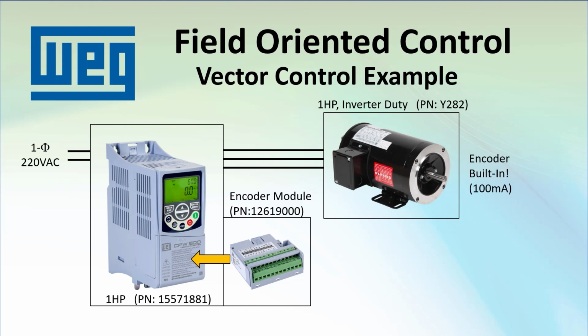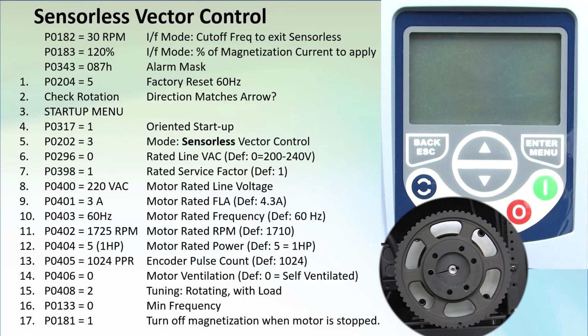And once again, I need to stress that all inverter duty or inverter rated motors are not created equal. It's critical that you choose the right motor for your VFD application, and in particular, choose the right motor for the mode the drive is using. To get the most out of these vector control modes, you need to have a motor that's optimized for vector control. This is what we need to do.